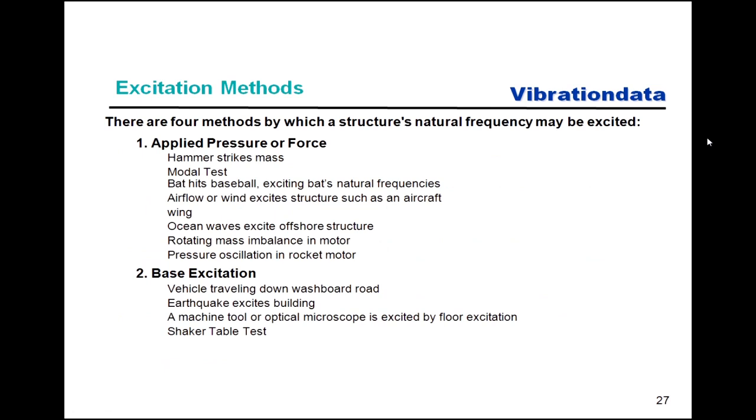We've talked about how structures' natural frequency can be excited. And for the purpose of this course, there are four main ways we can do that. One is an applied force or pressure. So think about acoustic pressure or wind pressure or a turbulent flow over an airfoil, for example. Or you could think of a modal test where, for example, an impulse hammer is used to strike an object.